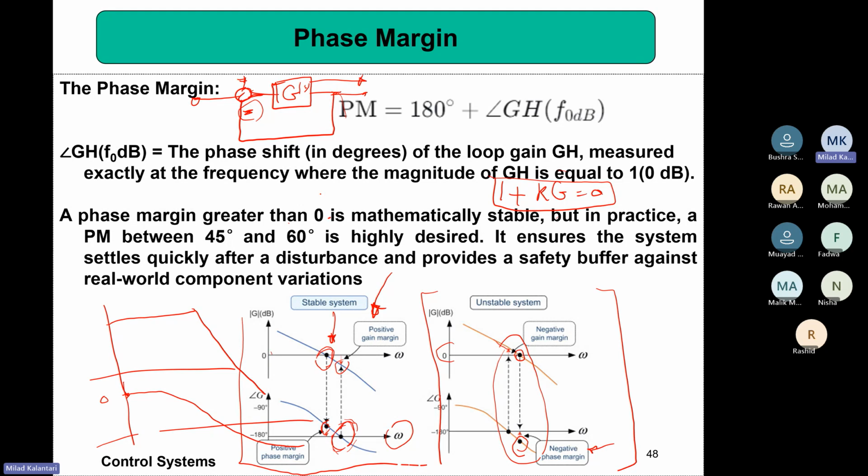So this case is saying the feedback is kind of positive in terms of the sign, but the gain of the system is not high, it is less than 1. Since the gain of the system is less than 1, it cannot boost anything inside the loop. It cannot grow the signal internally because there is no gain for that. The sign is positive, but there is no gain to build up.